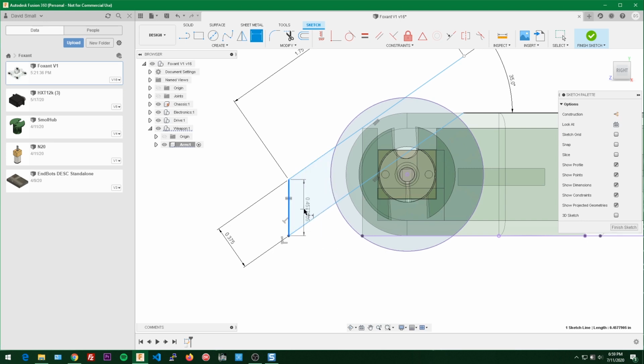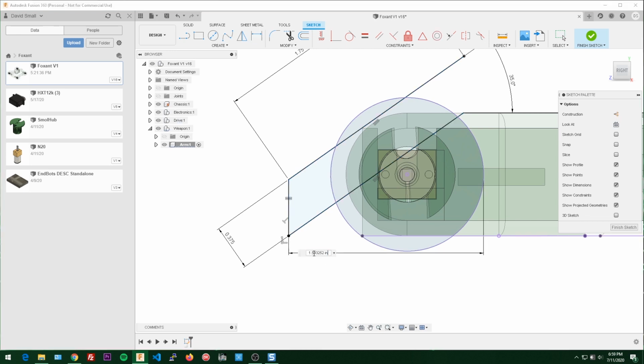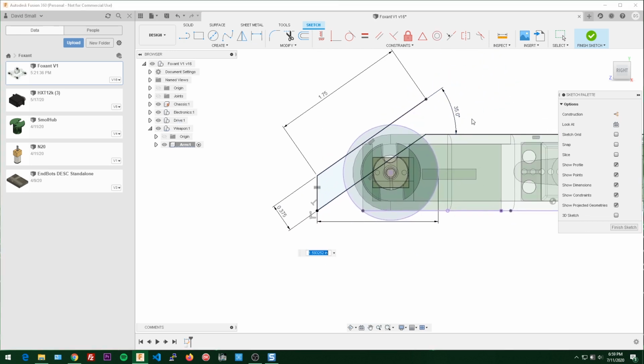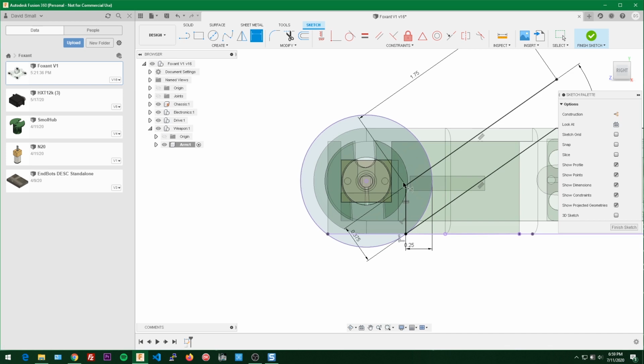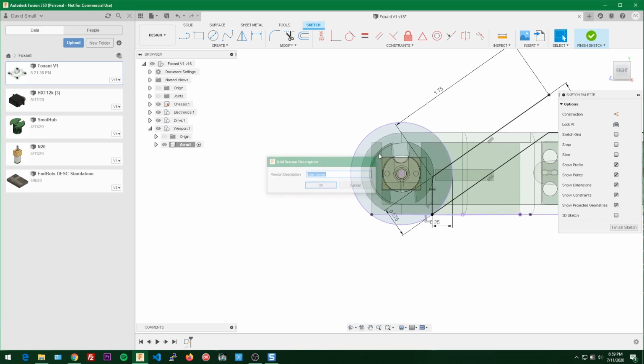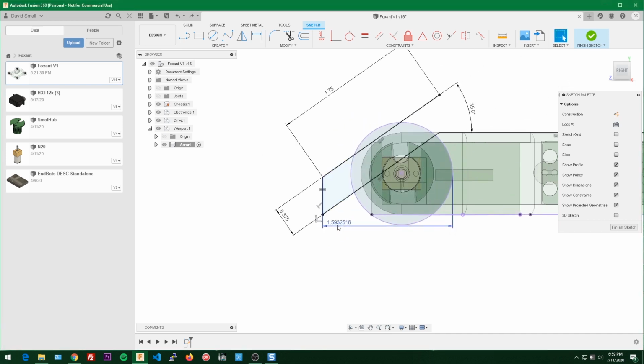and before you select the circle, right click, and they have this pick circle tangent option instead of pick circle center, which it's buggy or it doesn't work, because if you click on it, this looks like it's exactly what we need, but then when we finalize it, it shoots over here and defines itself on the right side instead of the left side, and now everything's broken. So we're gonna have to do this the lame way.